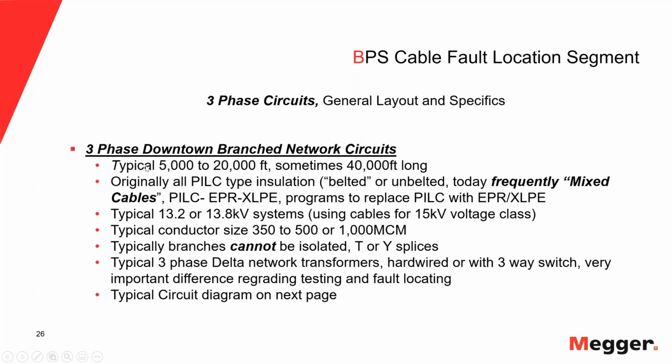And originally, because these downtown systems are the oldest systems, they are much older than any URD system, because they go back to the end of the 19th or early 20th century, right? So they are really old systems. And because they are really old systems, they have many times still paper cable in them. And when you have paper cables, Marshall mentioned already, there are two types of paper cable, belted and unbelted.